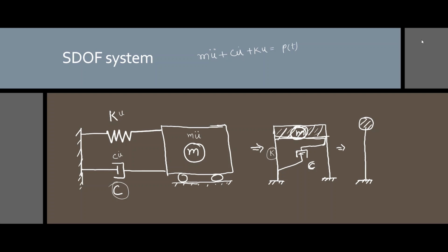We are interested in the stiffness of the column, so it provides the stiffness here, and the combination replicates these things, including the coefficient of friction, which is just for the damping case. So we generalize it with a simple diagram, an equivalent single degree of freedom system. These all represent a single degree of freedom system.